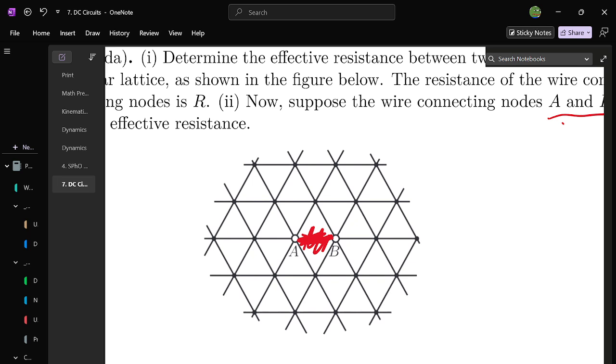You know that the resistance is R over 3. So part 1, R effective is R over 3. But in the scenario where this thing is cut, everything would have been symmetric if the thing was there. So why don't we use the idea of negative resistance to put the thing back there, but compensate with another resistor, in this case the negative resistance.